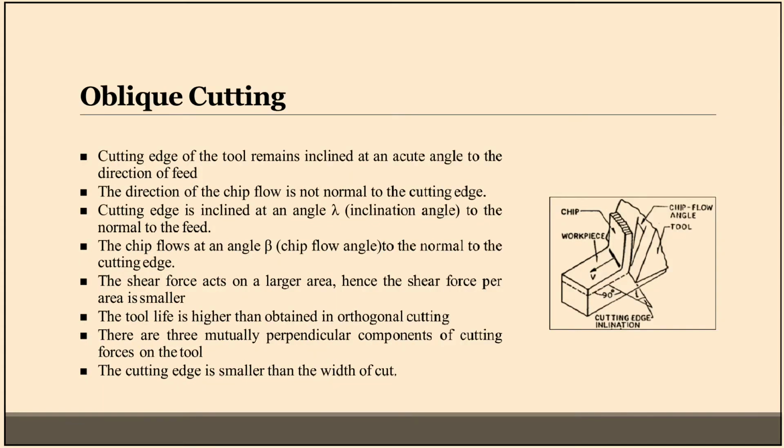Oblique cutting. The cutting edge of the tool remains inclined at an acute angle to the direction of feed. The direction of the chip flow is not normal to the cutting edge. The cutting edge is inclined at an angle lambda, the inclination angle, to the normal to the feed. The chip flows at an angle beta, the chip flow angle, to the normal to the cutting edge.